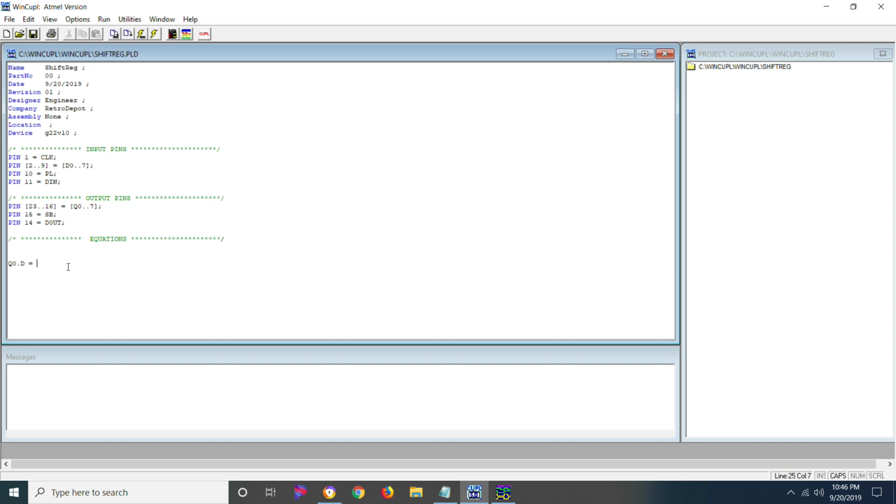Well, obviously, if we're writing a D. So what do we have to do to write a D? Well, we would obviously turn D0 high. We would change its state to high. We would want to pull the parallel load pin low, so that's when it would be high, at least when we're writing data to it.